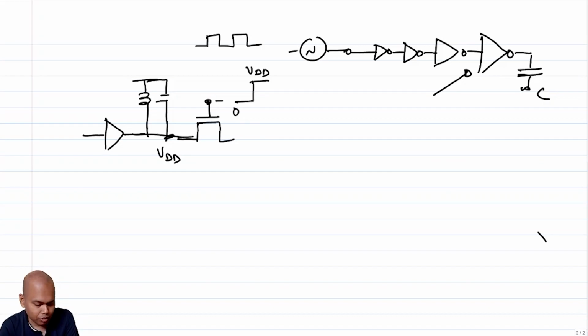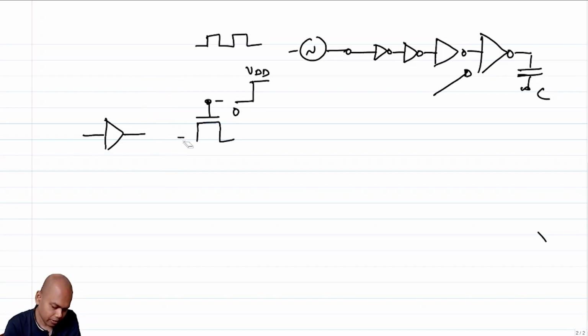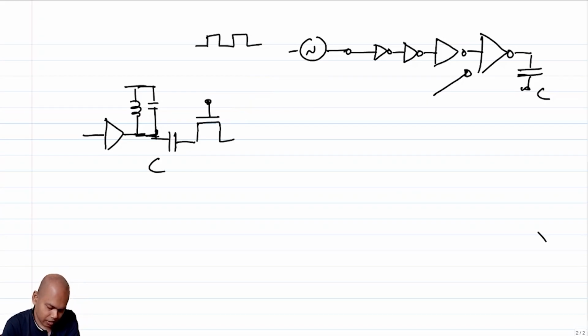But we understand that I don't need to couple a DC current, right? I am not looking for any DC signal. My signal is at RF, which means that I can have a different bias for the mixer and for the LNA and AC couple them, right? And how can I do that? I can simply not connect them directly. I can connect them through a capacitor, just like we do in any other analog circuits, right? So I call this C, let's say.